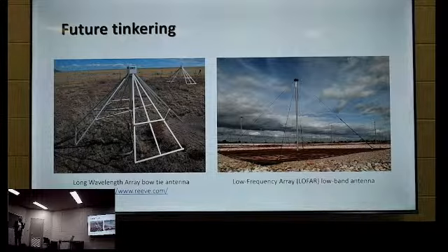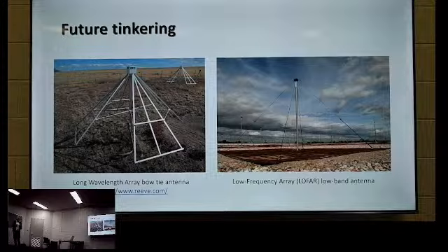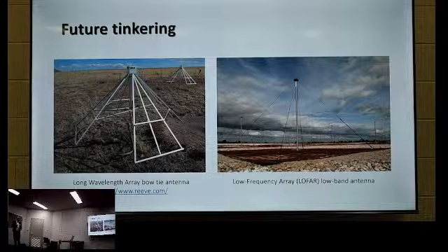A little dish I've got, an Ozstar dish, uses the K-band, where some of the Starlink satellites are up in the gigahertz range. It's got a wide bandwidth amplifier in it, and I've looked at other frequencies there. I looked at the Optus satellite out at geosynchronous orbit, and I've used that to measure rain attenuation, because at those frequencies the rain actually has an effect on the signal. So there are other exciting things you can do with radio.